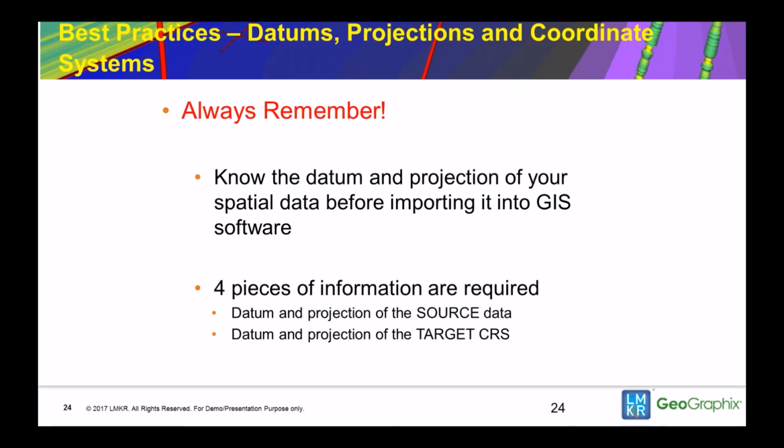Just right-click on the layer and select the datum shift, and you can go ahead and shift the datum. The dialog that you'll see is very, very similar to the one that you'll see in ArcMap, but just remember, just as in ArcMap, when you shift datums, every layer on the map is going to use that datum shift. So you have to sort of remember that.